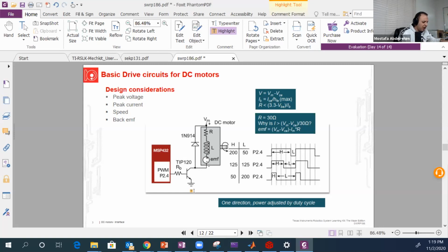So you can just draw it as a simple transistor like this. Now the input current which comes out of the microcontroller will be amplified in that branch, which is just the motor. The motor can be replaced in a circuit using a resistor, a coil, and the induced EMF. And what is this diode used for? This diode is used to reduce the amount of EMF that will be generated when you switch the motor on or off.